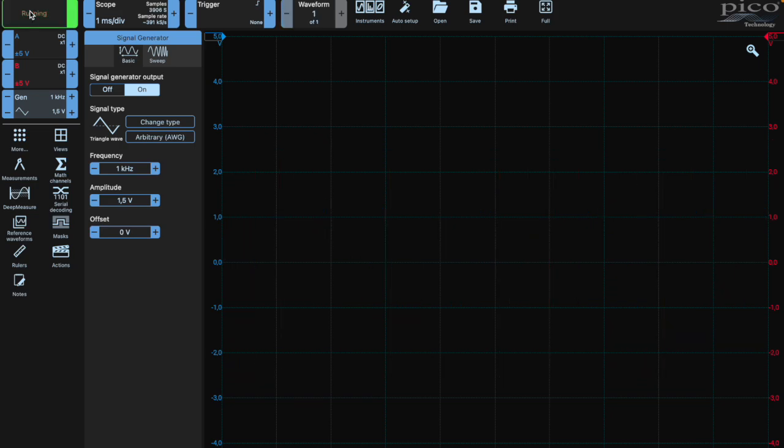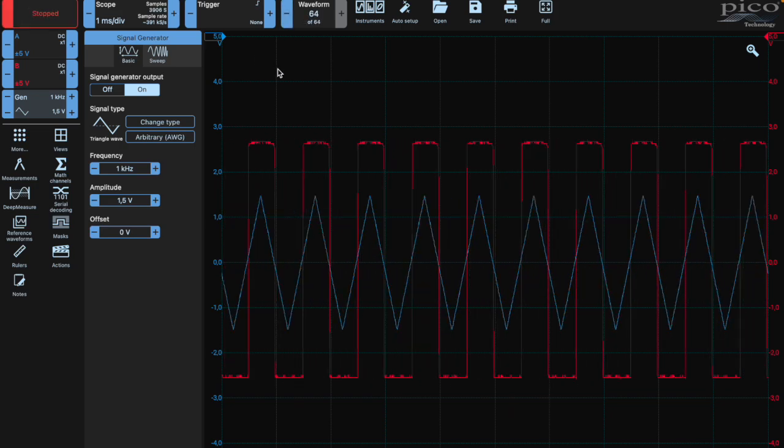Here, I'm triangulating the input, and when we do that, we see that the wave exceeds both thresholds, that is the upper and lower threshold of the Schmitt trigger. Therefore, the Schmitt trigger generates a fairly clean square wave at both crossings. So this was my lab 4, where I built a Schmitt trigger for my circuit using an operational amplifier.